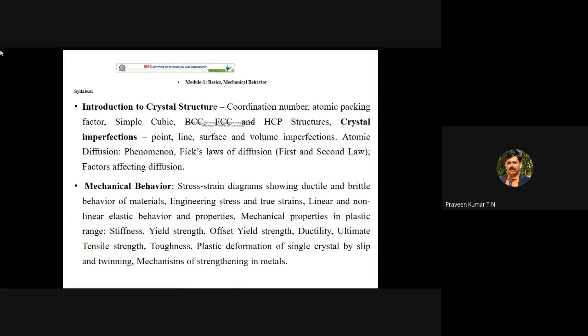For most metals, you studied the stress-strain curve up to the elastic limit and plastic limit. Your stress and strain are proportional according to Hooke's law. That is linear behavior up to the elastic limit. If you go beyond the elastic limit and apply more and more load, the material undergoes plastic deformation. Because of that, like rubber or plastic, you may not get a straight line.